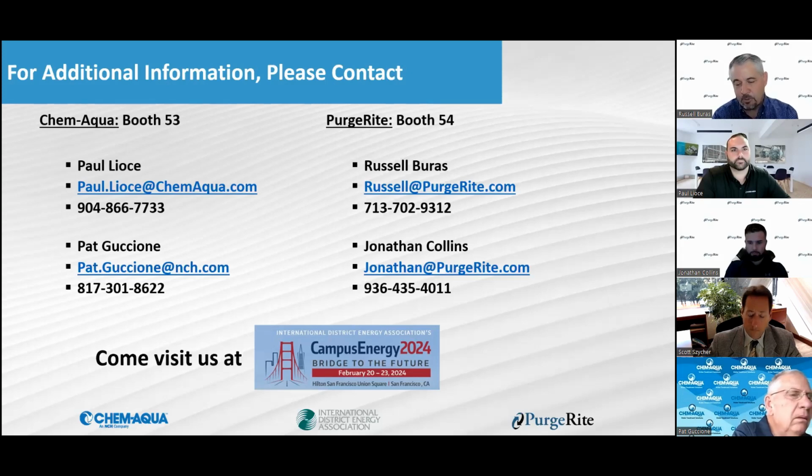So we're not a proponent and never have liked that procedure that has been out in the universe for many years. And we have found it to be much more effective and much better for the systems to actually bring in makeup water and discharge makeup water, all while circulating to dilute the chemistry down, get it back to the makeup water quality, insert your inhibitors before you and circulate those before you seal it up. So that's really the key thing there.